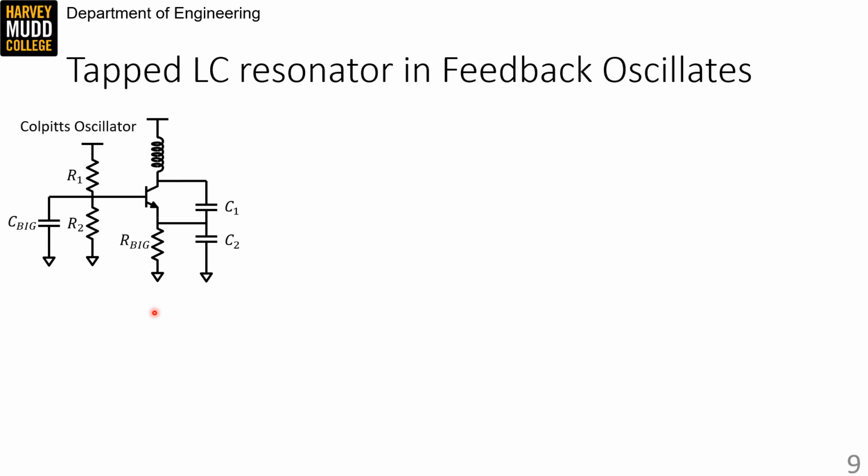There are also other kinds of oscillators, like Hartley oscillators, which use a tapped inductor feedback network, Clapp oscillators, which add a few more tuning capacitors to their resonator, and Pierce oscillators, which are often used with quartz crystal resonators. All of them work on similar principles to this Colpitts oscillator. If you understand one, you can figure out the rest.